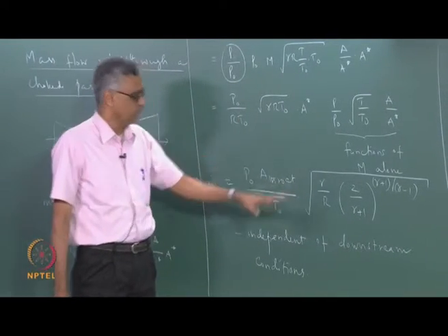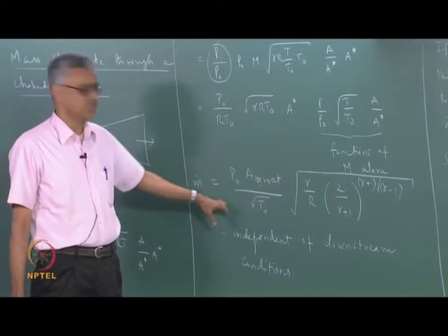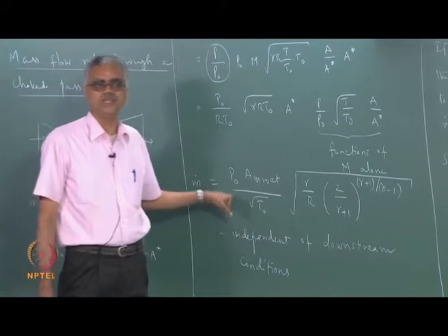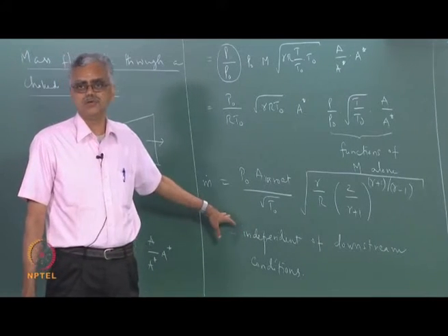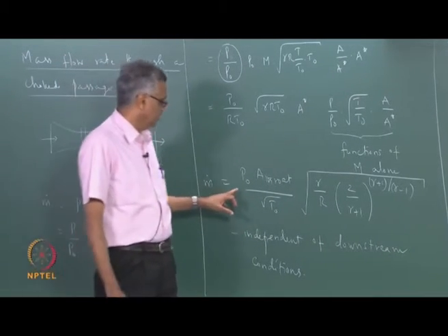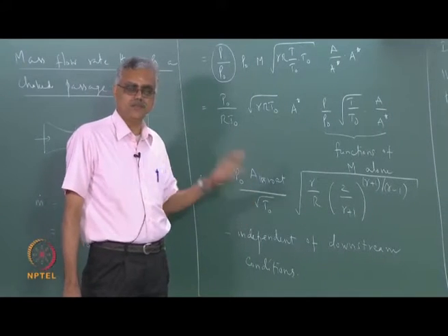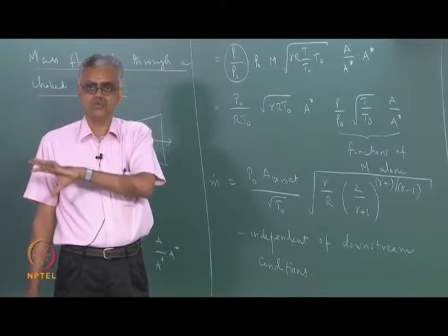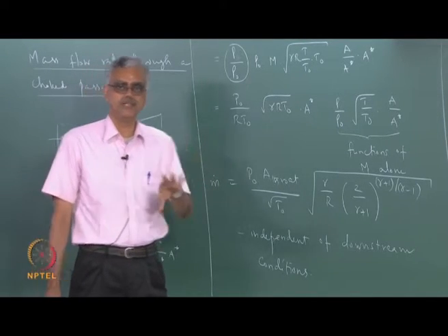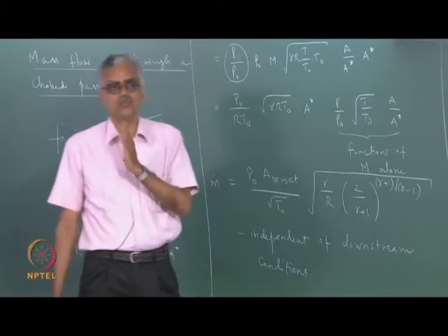Okay. We will actually have an opportunity to revisit this expression for mass flow rate many times during our discussion as we go along. This is an extremely important discussion, because what this tells me is that this is the mass flow rate that is going through, and in some cases when you have multiple throats, this expression will determine what flow solutions are possible downstream.